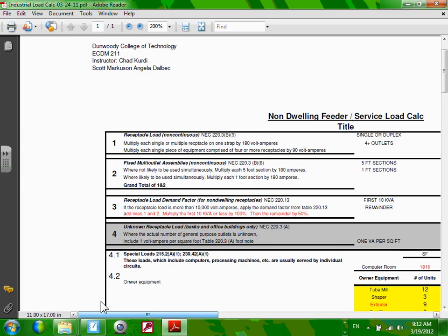The bus ducts, are they separate panels, or what are you referring to? A bus duct is basically a big copper bus coming out of the switch gear, and the load, it's like a panel, but it's really not a panel. It's a distributed load panel. So say I have 10 machines right here and I want to wire them, 2 options. I can wire them with a feeder from this panel, one feeder for each one of them, 10 feeders, option 1. Option 2 is a bus duct.